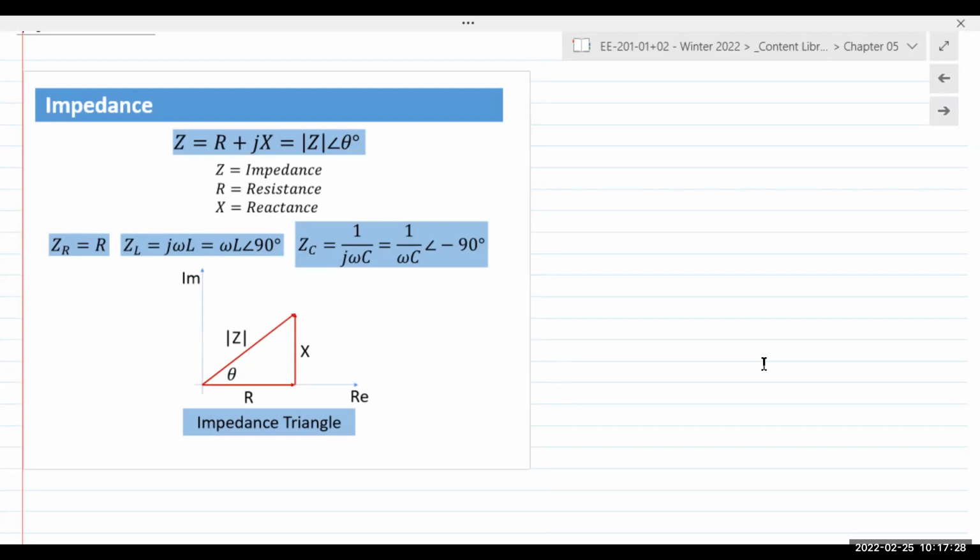If you start to change the voltage, the capacitor now starts charging or discharging in the other direction. So now current starts to flow. So the capacitor behaves exactly the opposite. When you start changing the voltage, it opposes the change in voltage, but it causes current to flow in that circuit. That is represented by the term called reactance, noted by uppercase X.